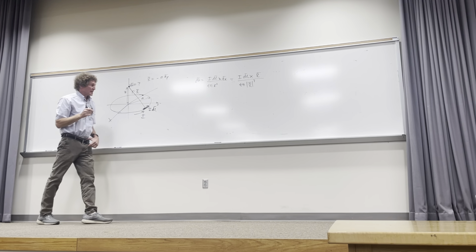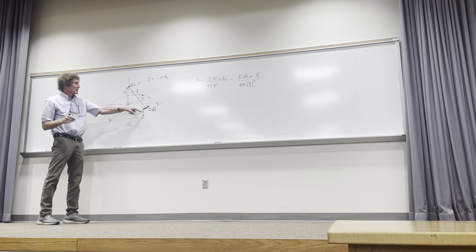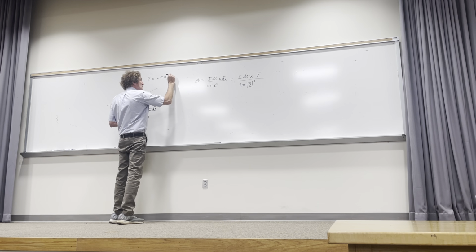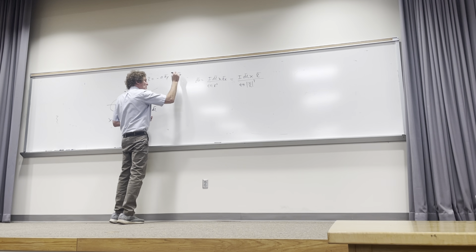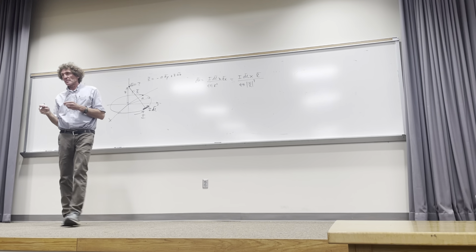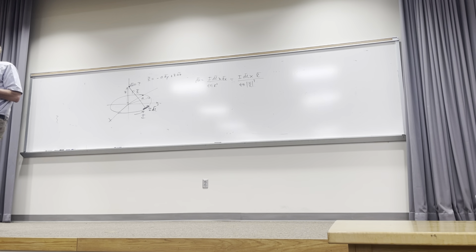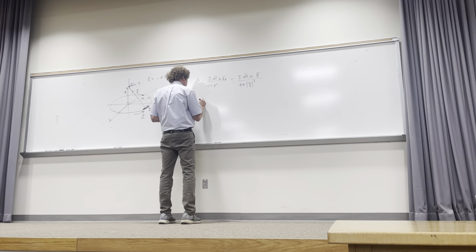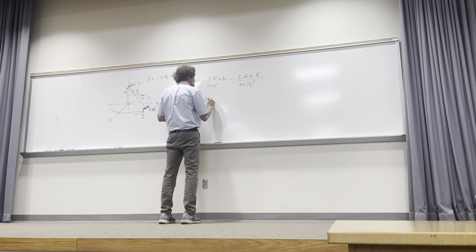And what about z? It said 0 here, and it's at height z here, so it'd be plus z a_z. You all agree with that? Now, because we're right on the z-axis, a phi loses its meaning. Don't even worry about a phi. And I'm going to make an argument of symmetry to get rid of that problem integral in a second. So I have this, and now I put this together for dH. And I see that dH is equal to